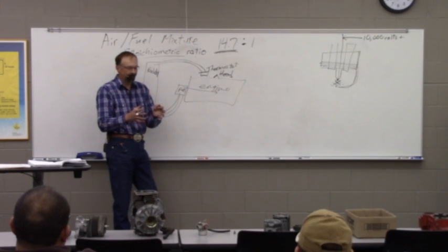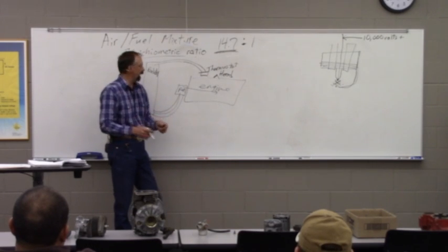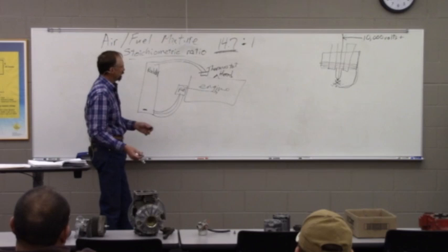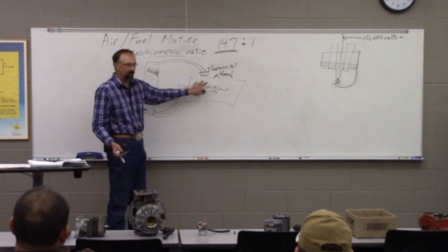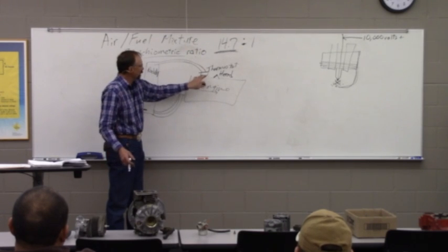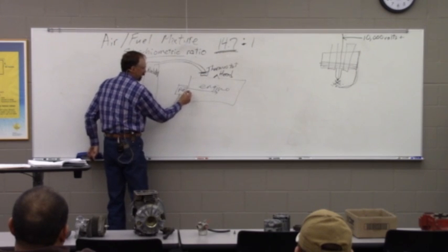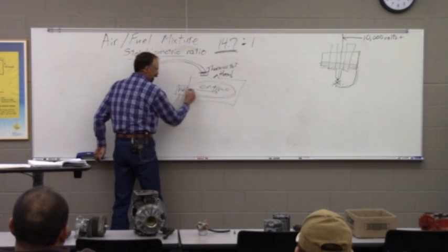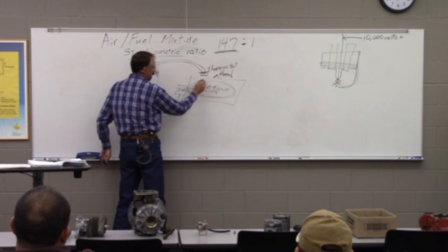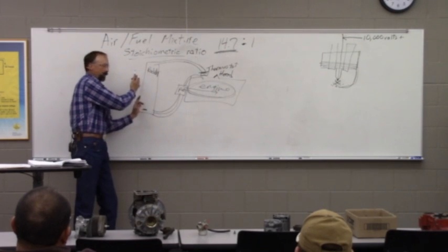And in most designs, 185, 190 degrees we'll have way better fuel efficiency and less emissions. And so we want to keep the temperature up somewhere in that range, like I said, 192 degrees is a common one. So whenever this is closed, this pump is actually just stirring and mixing the water in here. It'll push it. There'll be a little bypass hose that comes here, but we're not actually circulating through the radiator.